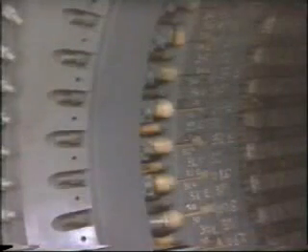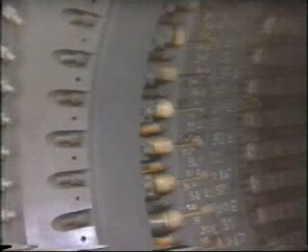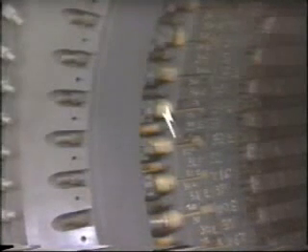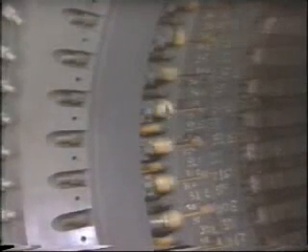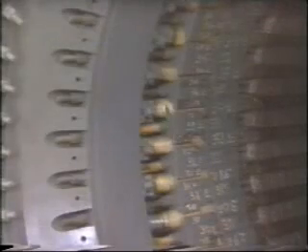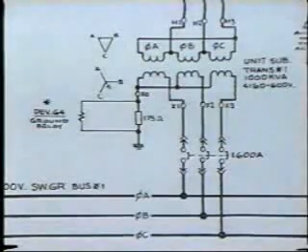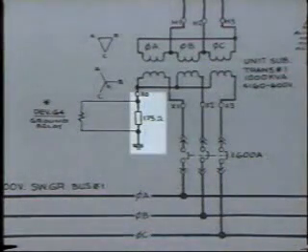For example, suppose the ground fault is in the generator winding itself. The very high fault current and resultant arc jumping from the winding to the stator laminations would probably burn and seriously damage the generator. We'll be discussing specific examples of impedance grounding in future tapes, but one point is very clear. When working on the power system, you must be alert for these various methods of grounding. Always check the schematic diagrams. The value of grounding resistance or impedance is usually indicated.